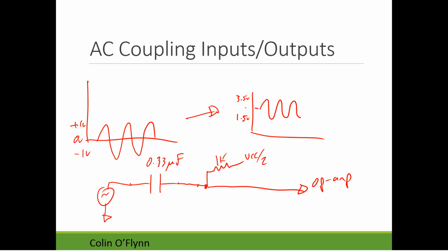The other option you could do that's even easier is you could, for example, just use 2 resistors, and you wouldn't want them to be too small. 10K and a 10K, and you have it between VCC and ground. So what's going to happen is these 2 resistors are setting up a voltage divider, and it's taking your signal.